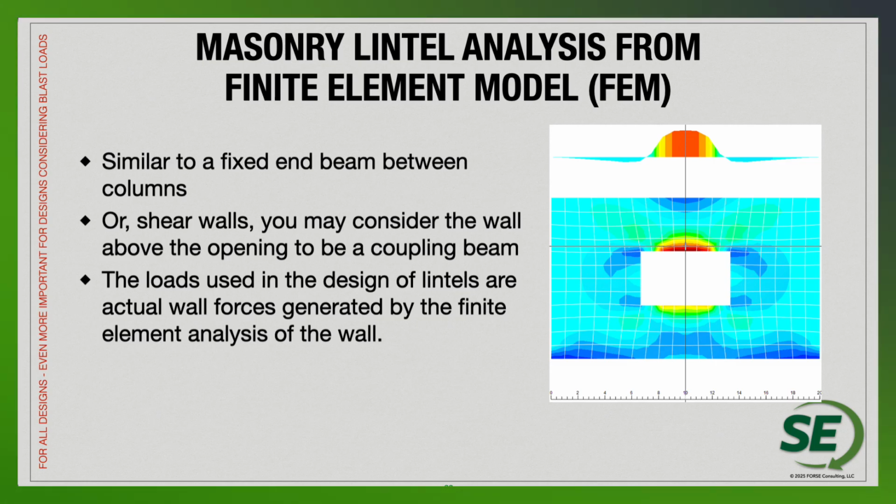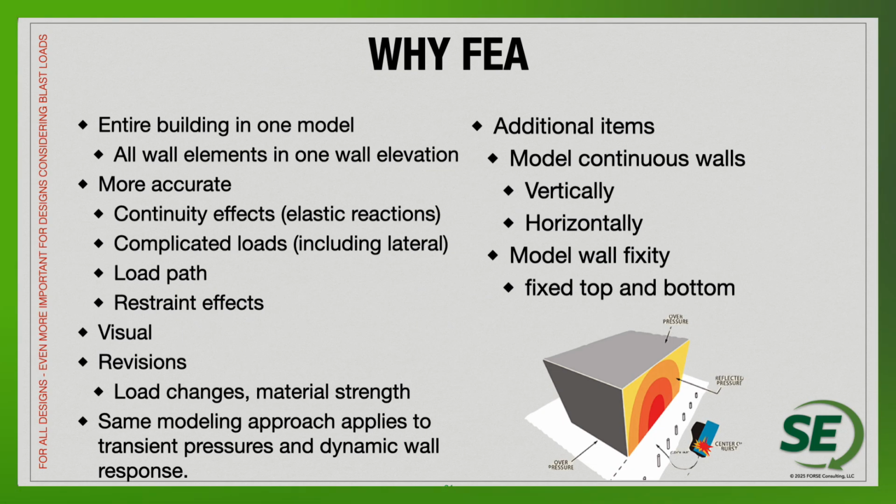So again, it's going to be really critical for the lintel design, but the finite element analysis is going to be really important for the overall analysis that we're looking at. So looking at the entire building in one model is going to be important for looking at the high impact loads or blast loads that you would have, understanding those high force situations and how that force carries through the rest of the building. So you can have a lot more accuracy when you use a finite element analysis versus a crude single element type of analysis that you may be typically used to doing with masonry design.